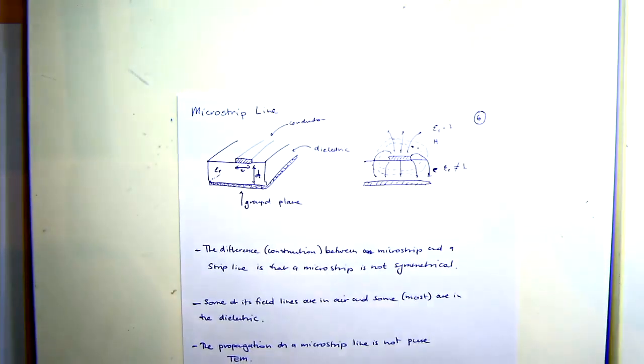In a strip line, you've got the same dielectric constant top and bottom. Here, I've got a material with one dielectric constant, and air on the top, right? I want to have somewhat similar analysis, but to make my life easier, I try to determine this concept of effective dielectric constant to simplify things.